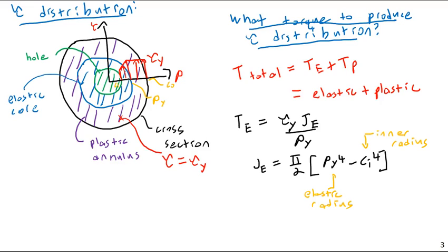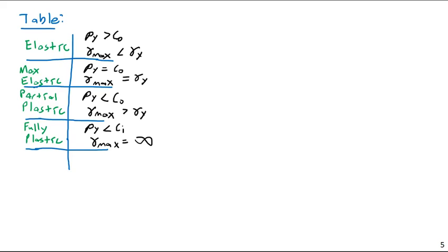So this would mean that we could apply any. What this means is when the entire section is in a plastic condition, we have reached the limit. We cannot apply any more load. Even the slightest additional load results in infinite deformation. This is really when something's almost at the point of, or at the point of failing, when any more load equals an infinite shear strain. Okay.